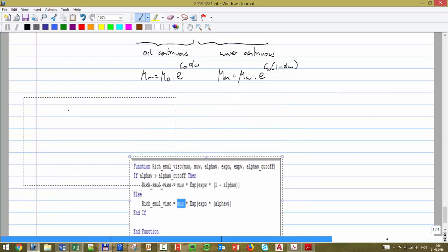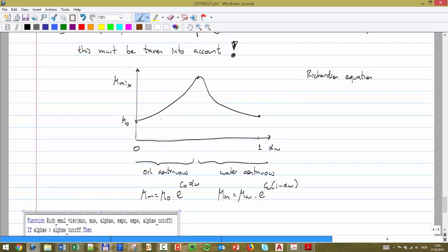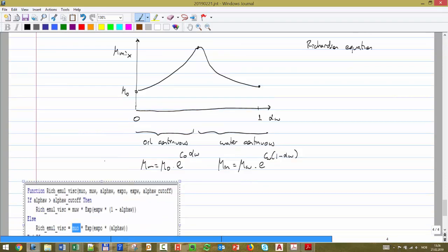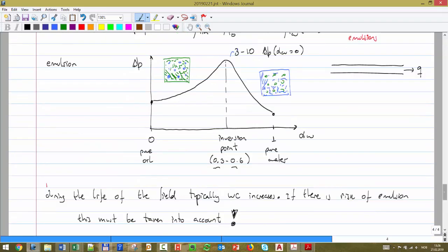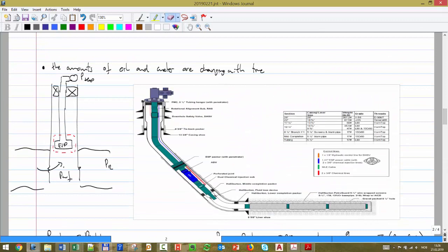Typically, besides being careful when I'm going to be around that point, we can also inject demulsifier, just to try to make the dispersion not so stable. In this field, the way it is done, they inject it at the suction of the pump. So they have to make a hole on the tubing hanger, and send a line with chemicals, demulsifier, all the way to the suction of the pump. Okay.